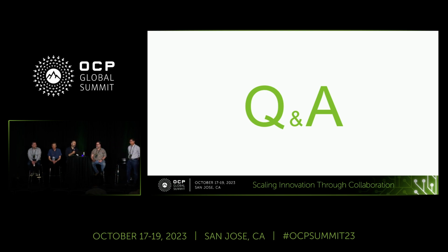Yeah, so for those of you that know me, you've probably heard me say this before many times. I think there's a really great opportunity for PCI Gen 6, not as a by-4 interface. It's for now that we've got CXL devices and other things that are sharing those PCIe or CXL lanes, the ability to have PCI Gen 6 on an SSD and maybe only run one lane to that. Now, we still need that to be 4 lanes on the drive because that's going to be backwards compatible. We're going to use that same drive in our previous platforms that are Gen 5 and maybe even Gen 4, because these platforms are revving so quick.